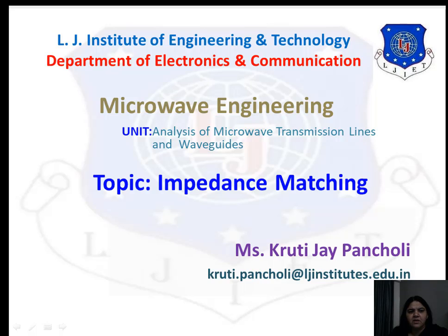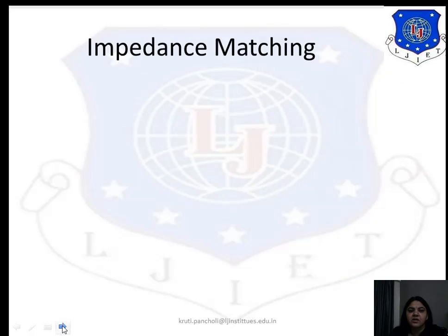Today we are going to discuss the basics of impedance matching. For the maximum power transfer from source to load, the resistance of the load should be equal to that of the source. The reactance of the load should be equal to that of the source, but opposite in sign. You have studied these things in the case of the maximum power transfer theorem.